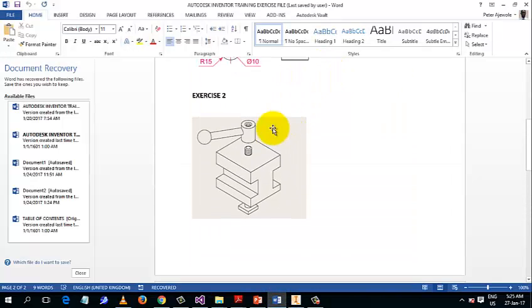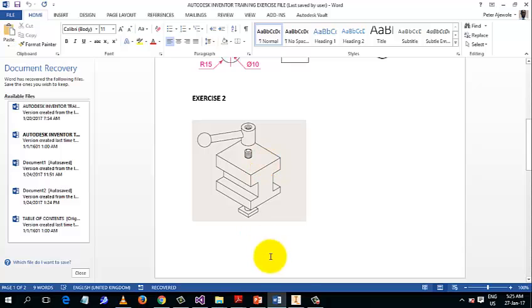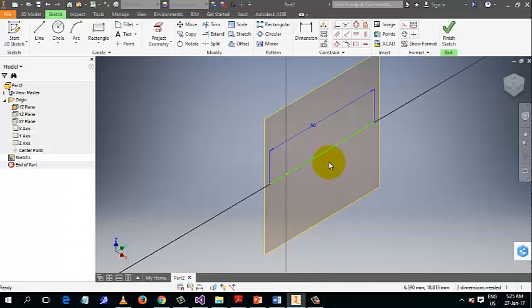So what I'm going to do is I'll come to the constraint. Then I'm going to click on this horizontal constraint. Click on it. I will select the midpoint. The midpoint will be highlighted in a green dot there. Click on the green. Then come to the origin. Then click on it. They will be aligned together horizontally.